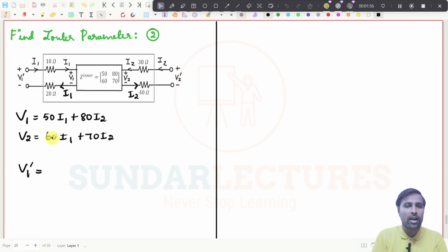So what will happen now? You are going in the opposite direction, so it will be 20 I1. Then I am traveling from minus to plus, so it will be plus V1. And then the direction is again opposite to the current, so it will be plus 10 I1. So now this is the equation. So what is V1 dash now?